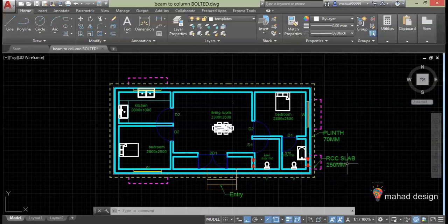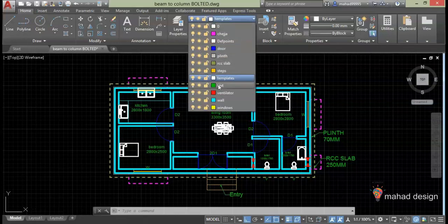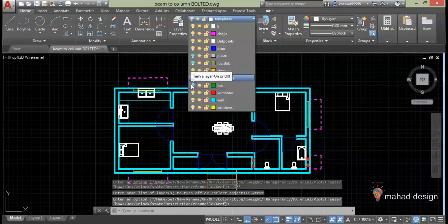In this case, I'll use the front elevation. So this will be the elevation which we will make, and for that I will start by hiding these dimensions and the text. You can simply do that by hiding the layer. Here we have the text layer and the dim layer. Let's click this light bulb as well as text so that we hide both of these objects.